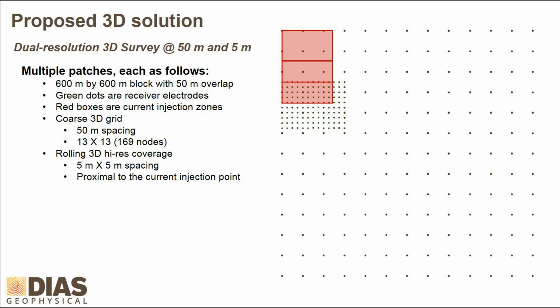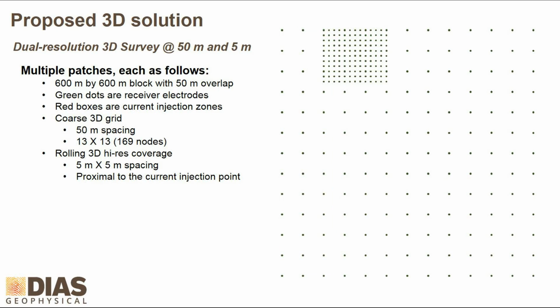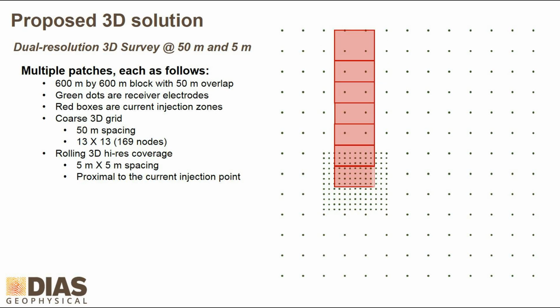area. So in this way, the area in and around your transmitter injection point is well populated by receivers. That's where you need your resolution, and then you've got a nice wider spacing of electrodes that are more distal. So you're guaranteed a better signal, and you don't really need the resolution in those larger offset transmitter-receiver separations.